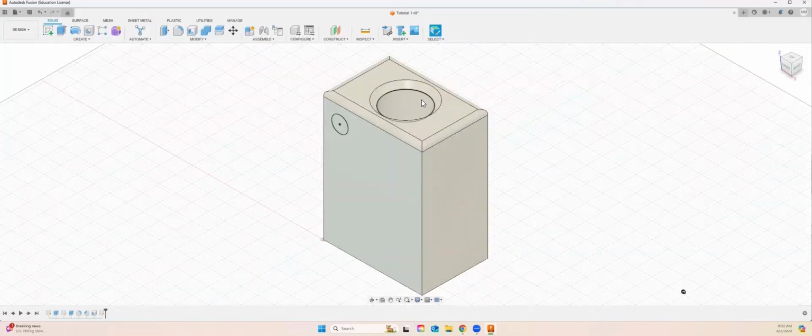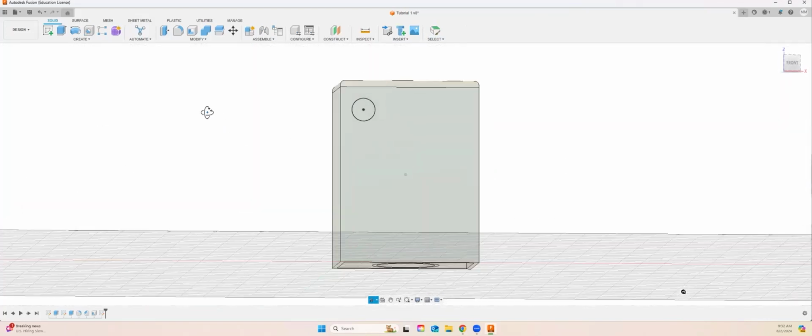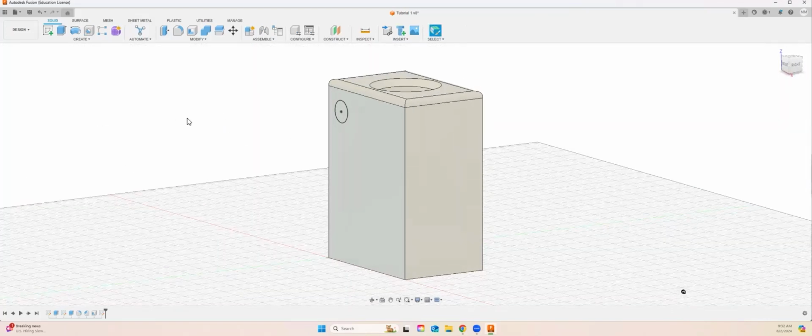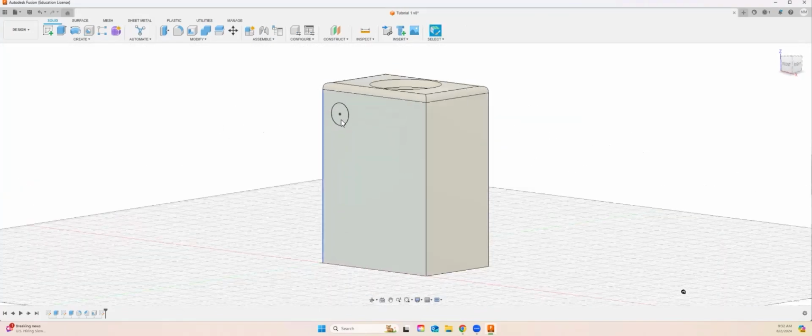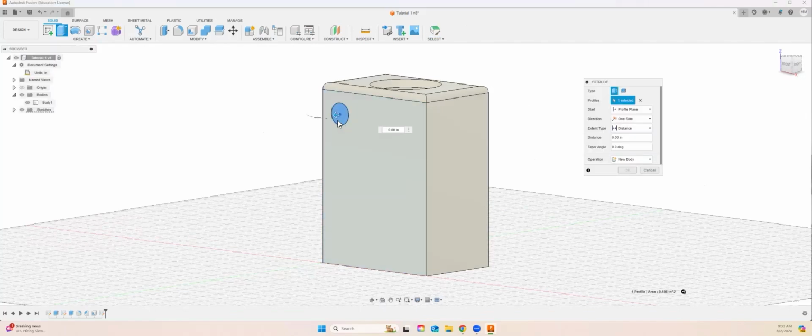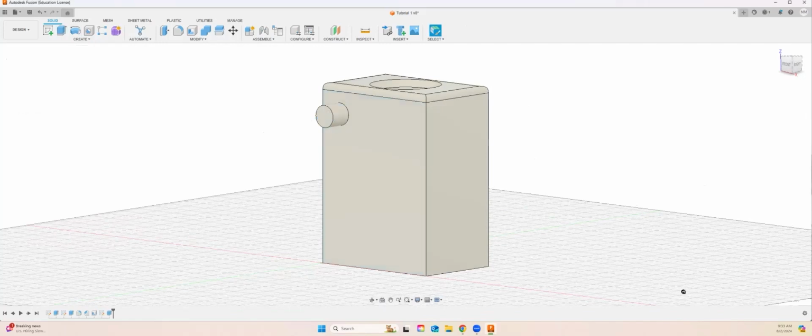So I click OK. And I can do the pattern now with the drawings, but I think the easiest way to do the patterns is you make your whole feature first, and then you pattern your whole feature, so you don't have to do a bunch of them individually. So I will do an extrusion from this part, and I'll extrude out. Let's say 0.5. That's fine.